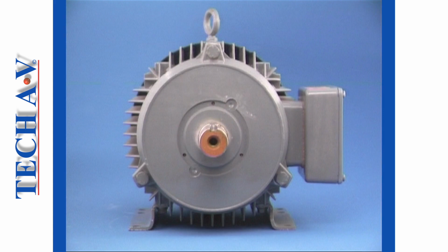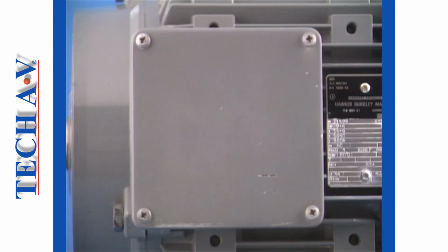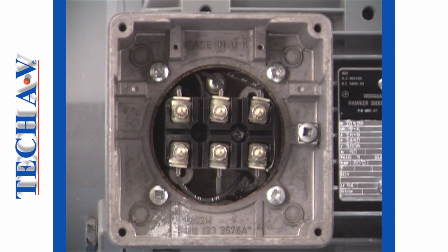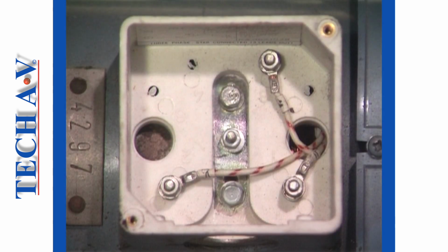Attached to the stator housing is the terminal box. It is here that the supply cable is secured and terminated. The cover of the terminal box is removable for access to the terminal board, upon which the supply is connected to the phase end terminals. Some motors, however, may be internally wound in star or delta configuration.